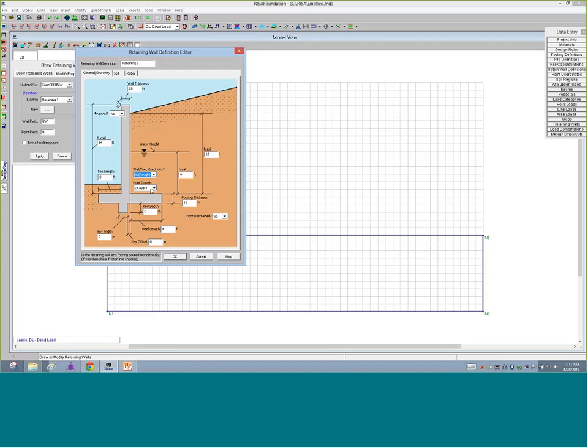We'll make that assumption. The dowels that you want to do, 1 or 2 layers into the footing. Now, if you need a key, that's where you can enter in this value. So first thing probably we'll do in most designs, you're going to probably start without a key unless you really know you need one. So we'll just say no key for now, and we'll see if it works without that.